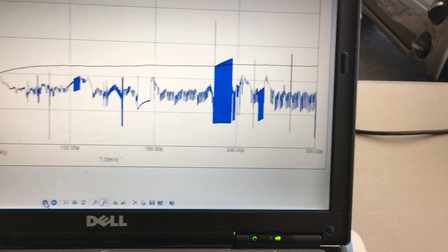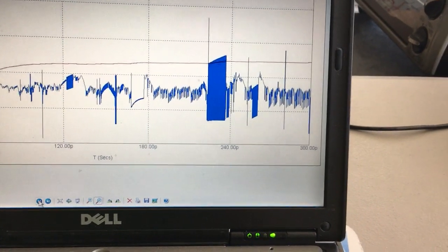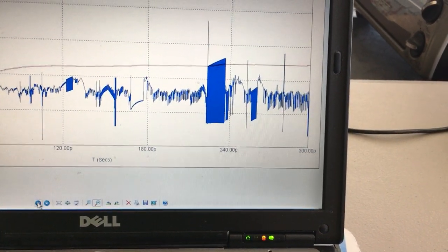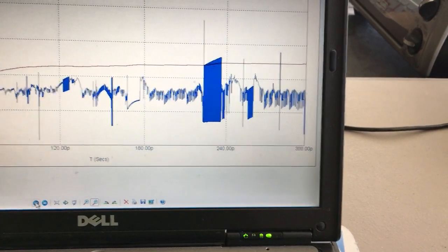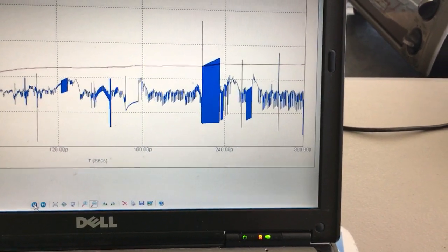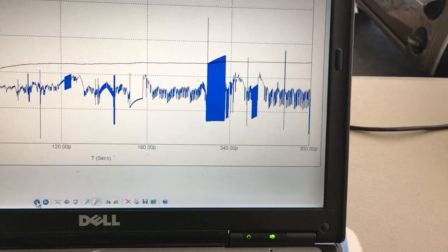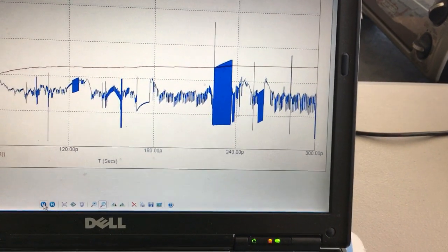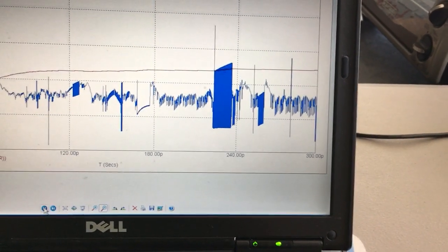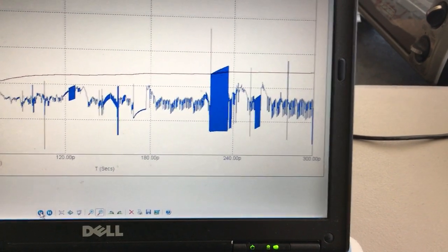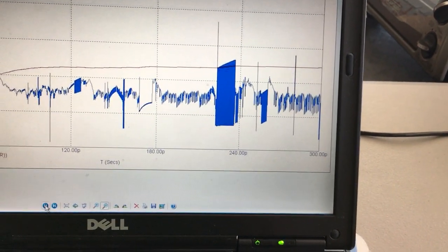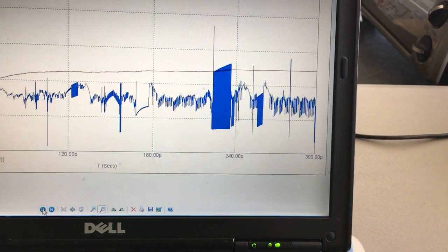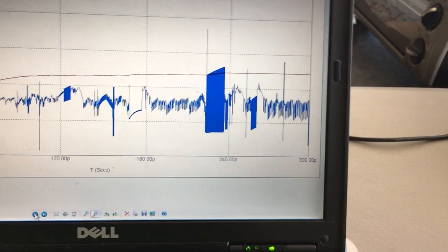So most of it, just about all of it, in this particular instance, because when you analyze this thing early on, very often you'll find triangle waves. I don't have a screenshot of that, sorry to say. I did it on earlier versions of this to satisfy myself that I was creating triangle waves, and the current and the voltage were lockstep, 0 degrees phase relation between them. Thus I knew it was capacitive reactance that's driving this circuit, not inductive. That's why it's so explosive, and that's why I get triangle waves with 0 phase difference between the current and the voltage portions of the wave.